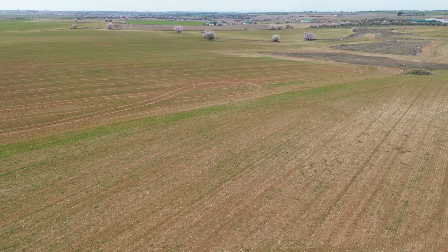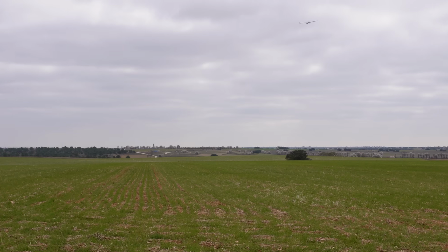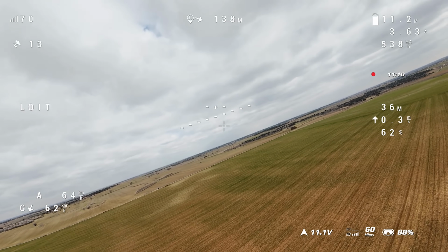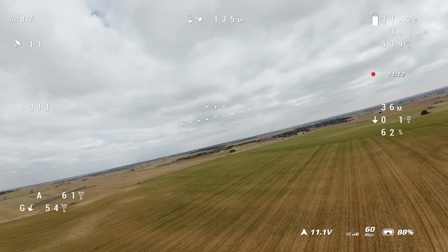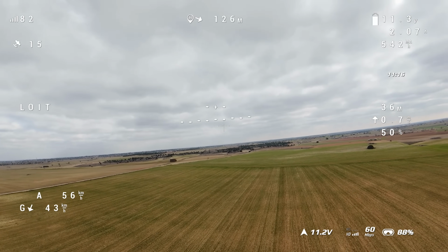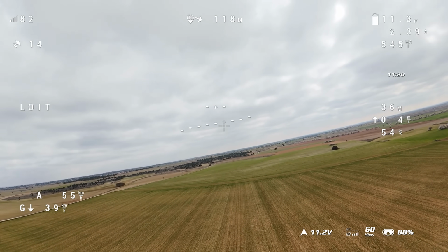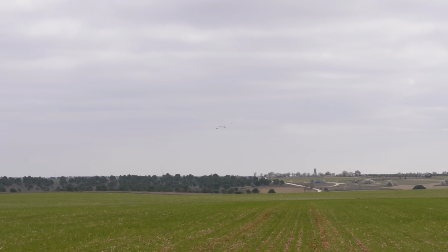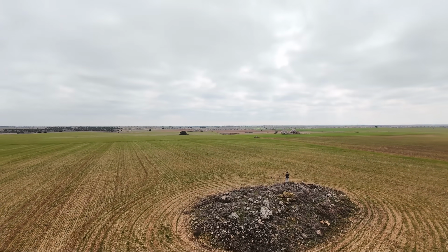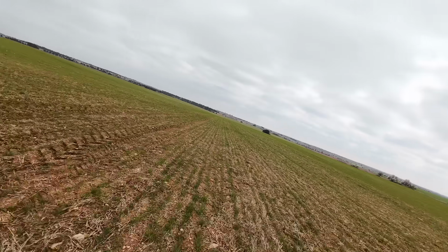It really flew amazingly. This thing is a gliding beast, able to easily maintain altitude with just a small amount of throttle. It feels so stable that I barely need to touch the controls. The wind didn't make it easy for the Maiden, but if anything, it proved a point. Even in gusty conditions, the NX2 stayed composed and predictable. That means we've hit the lateral directional stability targets we were aiming for, and maybe even surpassed them.